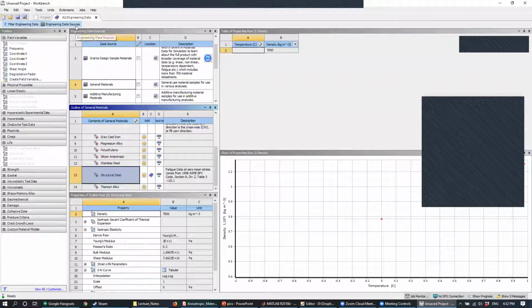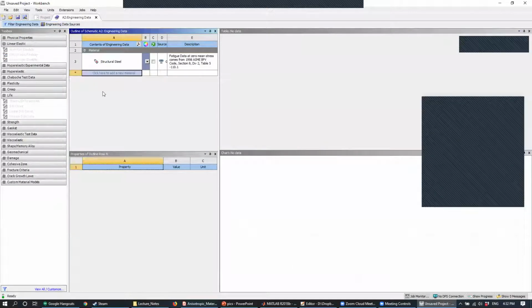In order for us to account for them, we can either input them manually, which is what I'm going to show you today. Or what I'm starting to notice is that if you subscribe to some of these material databases online, some of them offer a service where you can download a specific file, and then from that file, you can add that material property to your Ansys database. I've never actually tried that, but I did see an Ansys button on there. So if you know any good material databases online, that's something that you could look up and exploit for your project. I personally never used that, so I definitely want to give it a try before I show you guys. But that's something that you guys can look into for your project if that's going to be useful.